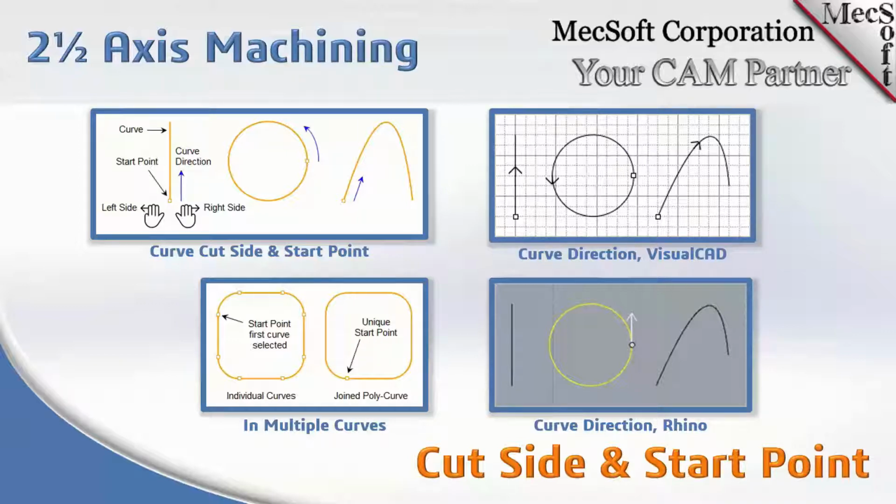On the right, you'll see that it has a merged curve, with one start point, and it's closed continuously. That is the method you really want to strive for if you're going to do any curve machining with more than one curve. So always remember to join your curves or merge them together.